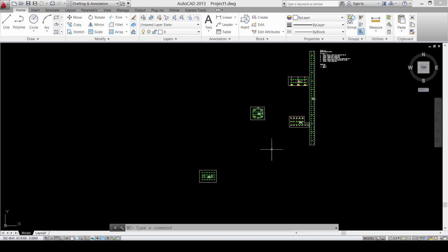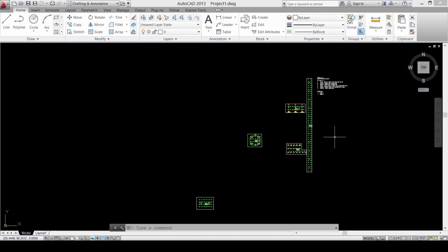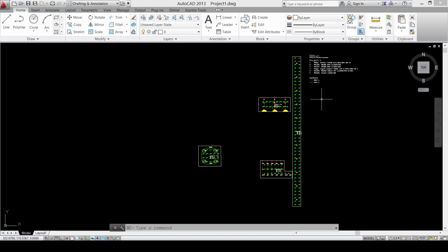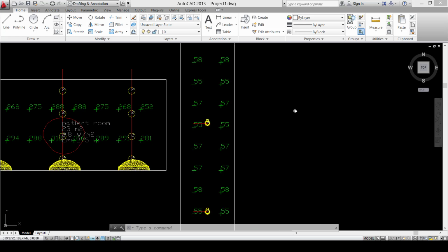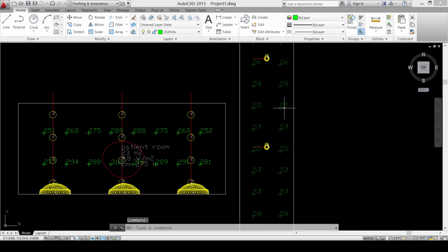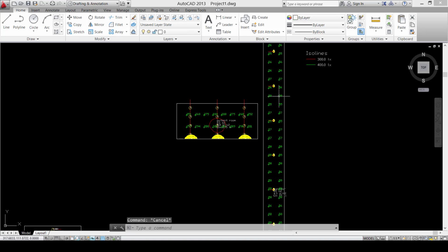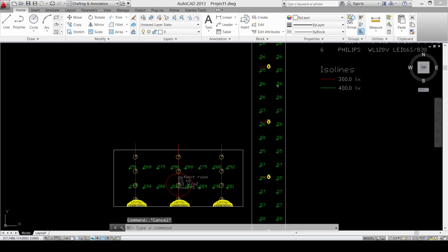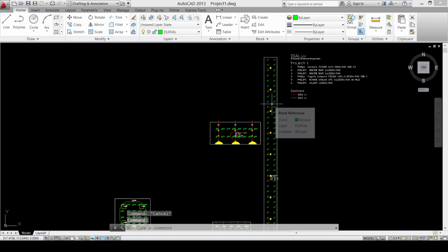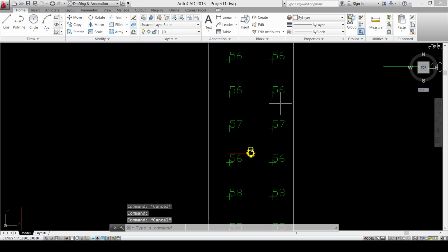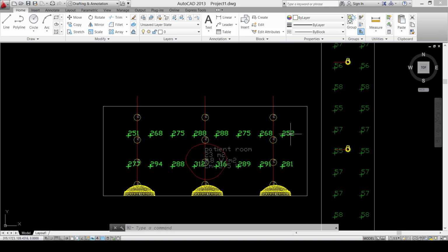But as you can see, those luminaires which we have exported from the DIALux software have some extra details, like those details here, which are the distribution of the lux on the different areas of the room. So for the corridor, this is the distribution value of the lux on its different areas. It lies here in green.